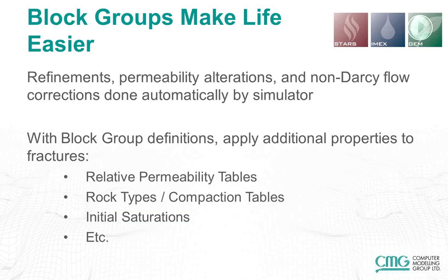And like I said, now that we can refer to the fractures by name, we can associate other properties to these fractures, such as different relative permeability tables, different rock types or compaction tables for modeling the closure of fractures, as well as specifying different initial fluid saturations so we can initialize the hydraulic fractures with the frac fluid. And really any of the other properties that we add into our simulation model, we can also specify using these block groups.